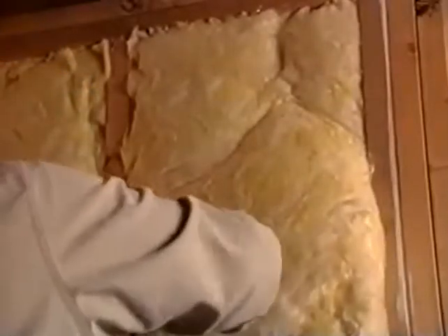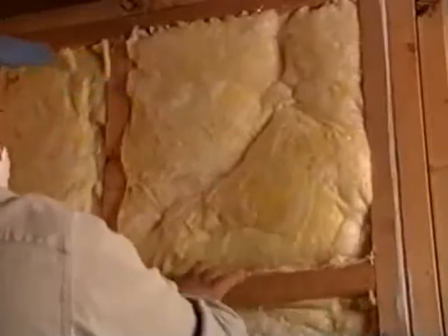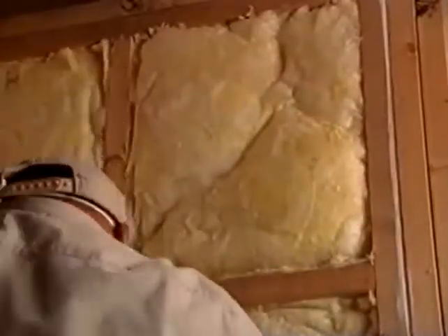It is important to never force insulation into any spot. Instead, it should be carefully placed into the stud cavity, allowing it to maintain its full thickness and achieve its rated R value. When electrical wires or plumbing pipes are in the stud cavity, separate the insulation in the middle. Pull the back half of the batt behind the wire or pipe. Take the front half of the batt and place it on top of the wires and pipe.